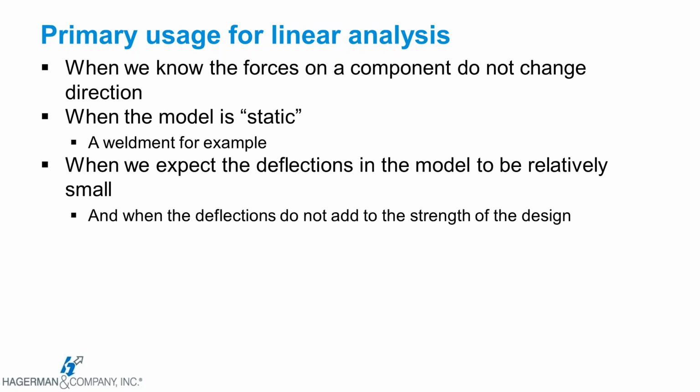The other big aspect about linear analysis is we don't expect the model to deflect a huge amount. Usually about 1/20th of the longest dimension is really all we're expecting for deflection, or less. Beyond that, if the deformation of that component starts to get into larger values, it's not contributing to the strength of that component. So, some of the general assumptions, as I was mentioning: the model doesn't move in a way that changes contacts, or they are already in contact with the components that they're going to be interacting with.